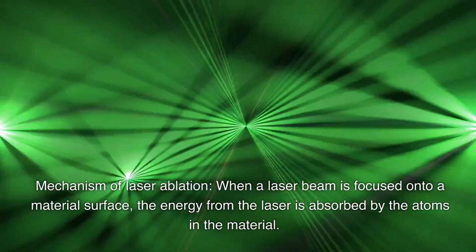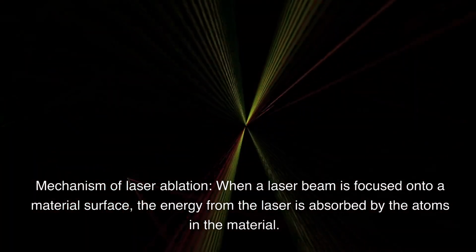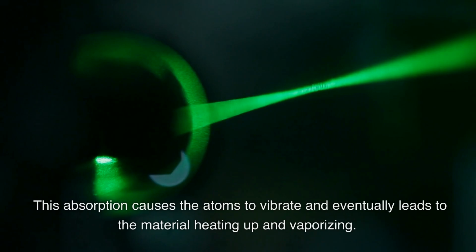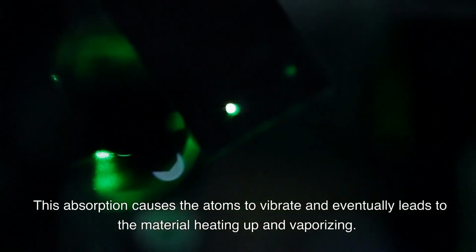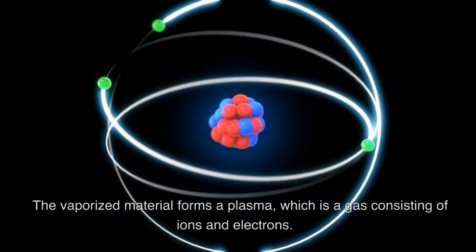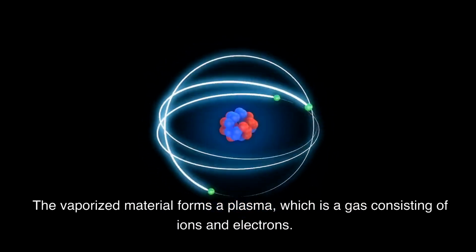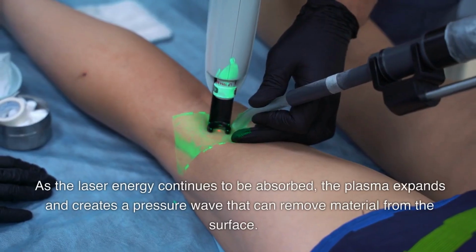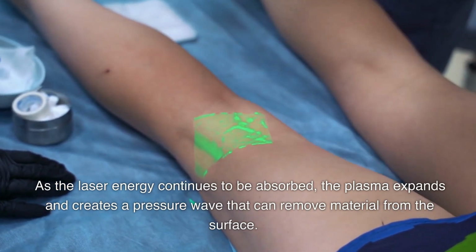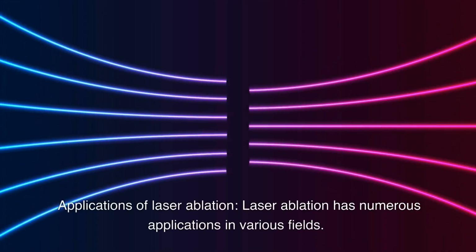Mechanism of laser ablation. When a laser beam is focused onto a material surface, the energy from the laser is absorbed by the atoms in the material. This absorption causes the atoms to vibrate and eventually leads to the material heating up and vaporizing. The vaporized material forms a plasma, which is a gas consisting of ions and electrons. As the laser energy continues to be absorbed, the plasma expands and creates a pressure wave that can remove material from the surface.